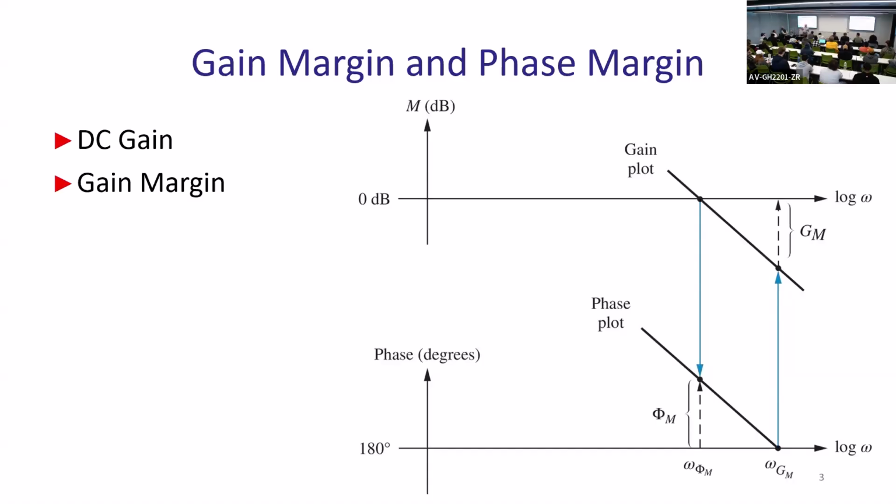Let's assume you have multiple points like that, then what gain margin is? Let's say it's crossing multiple times, going up, down, depends on the number of poles here and there. What would you take as gain margin of that system? The average of all of them? No, not average. It'll be the same. You're taking worst case, worst gain margin out of all of them.